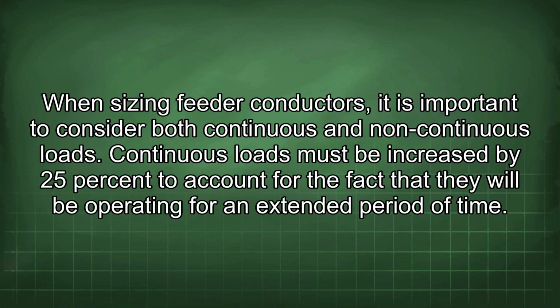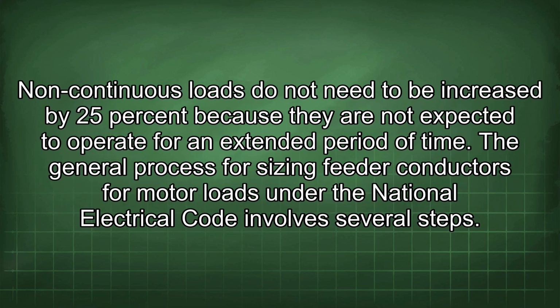When sizing feeder conductors, it is important to consider both continuous and non-continuous loads. Continuous loads must be increased by 25% to account for the fact that they will be operating for an extended period of time. Non-continuous loads do not need to be increased by 25% because they are not expected to operate for an extended period of time.